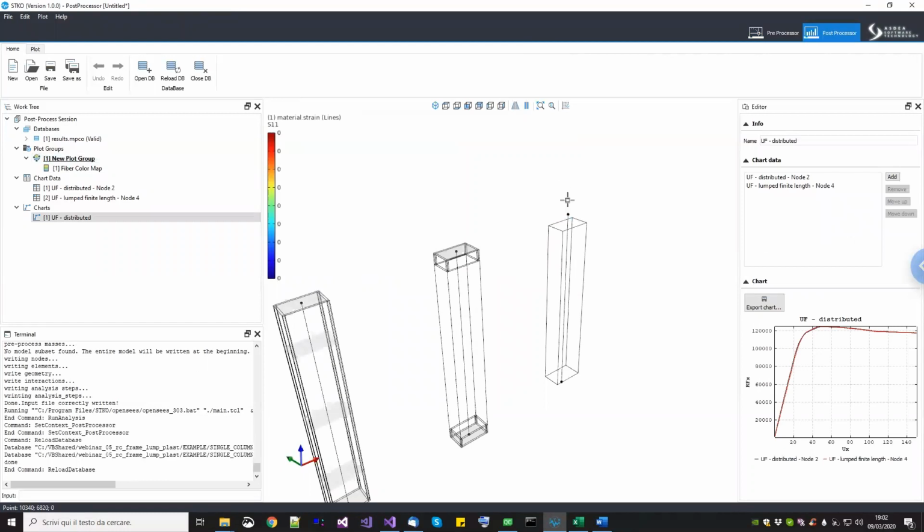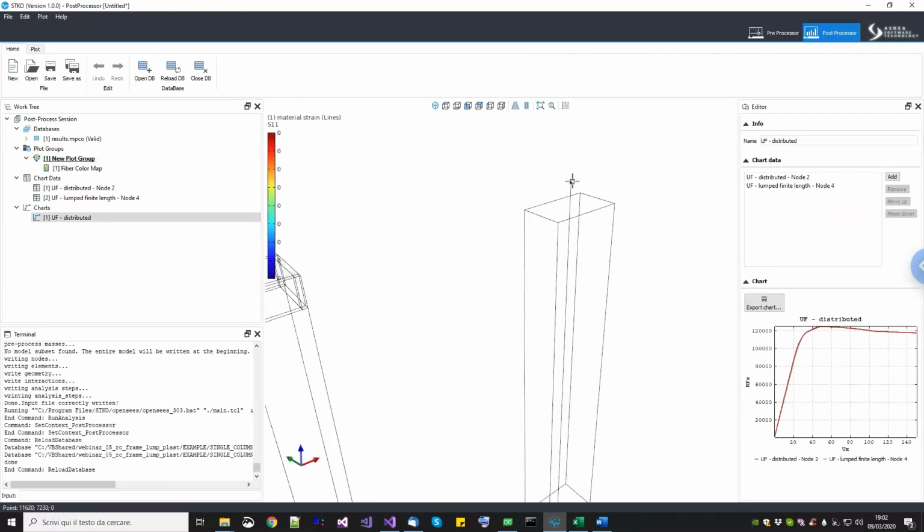So we select. Now, of course, if you go here you understand where is the difference. If I click here, it's okay, what you want to select? The node number 6, which is the one created in STKO, or the node number 8. Now, this one is the extra node created by STKO, so that between node 8 and node 7 and node 6, there is the zero length.